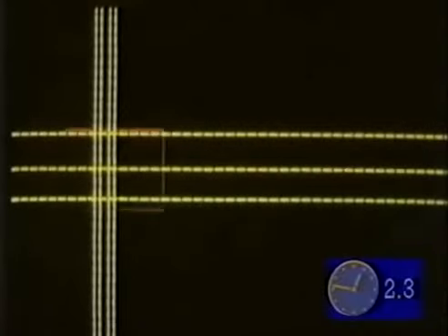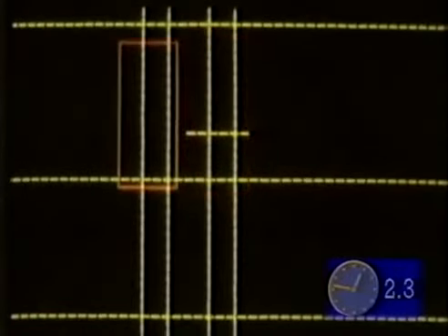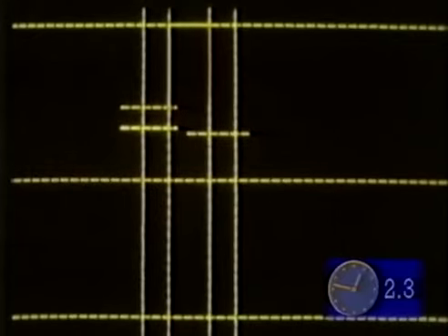Alan selects a small area that he'd like to work on in more detail. He identifies with a box the area he wants to work on and adds in further offset construction lines which identify the exact profile of the cover's section. When he's happy that these are correct, he gets the system to draw a continuous line over those parts of the construction lines which correspond to the outline of the cover.